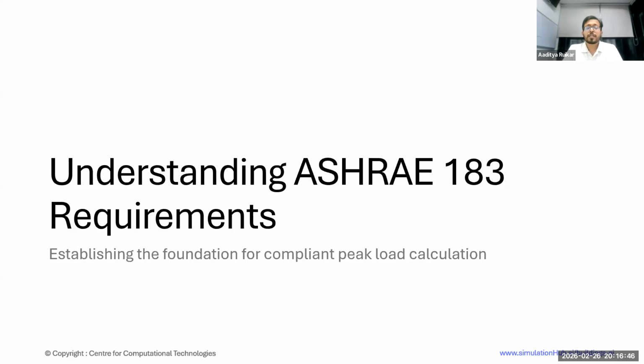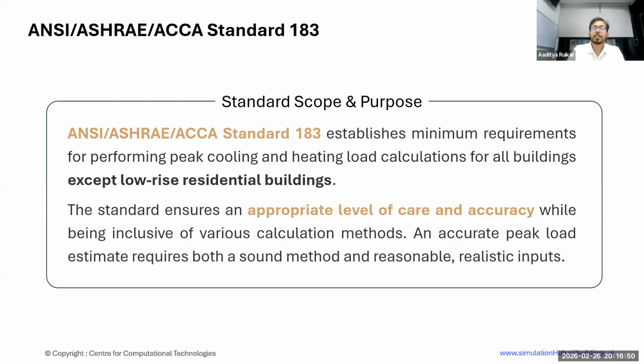So understanding ASHRAE 183. ASHRAE 183 doesn't specify that you should go with only one method, but it suggests the heat balance method. So we'll look at the purpose and scope of this standard. This standard doesn't say which method you should go for. It establishes minimum requirements for performing peak cooling and heating load calculations.